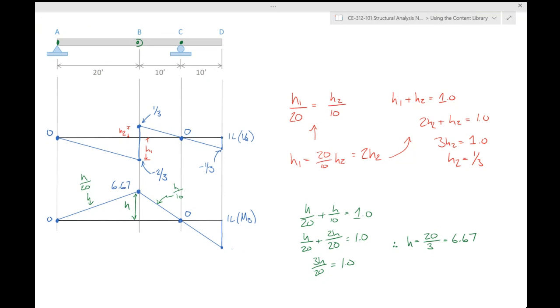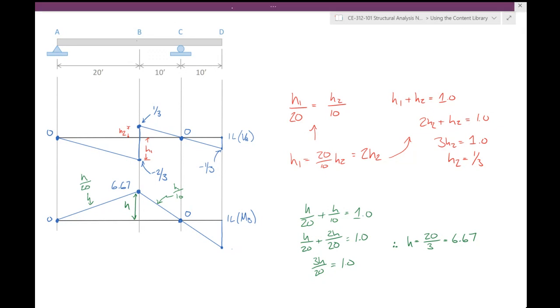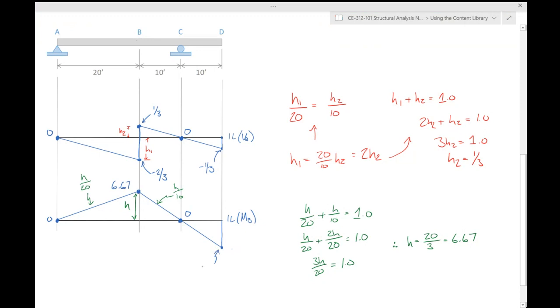They're the internal response as the load moves. The hinge and the shear release and whatnot are mathematical tricks where you draw those influence lines, but again, they're not moment diagrams, and that's the kicker. What I'm saying is this is the internal moment at B as the load moves across the structure. Now I'm just curious, and then I really want to attack the second problem here. What do you think that point is right there? Let's see if anybody's paying attention. What's that point?